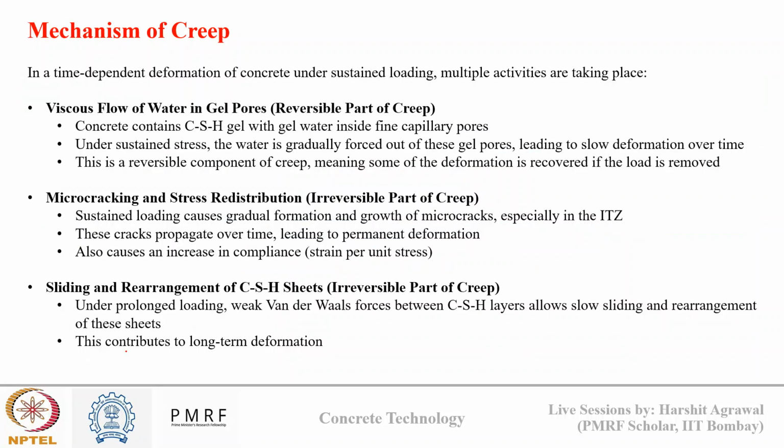Now let us try to understand what Lyman was trying to say in his three possible causes. In the time dependent deformation of concrete under sustained loading, multiple activities are taking place. There is a viscous flow of water in gel pores, which is the reversible part of creep. Concrete contains CSH gel with gel water inside fine capillary pores.